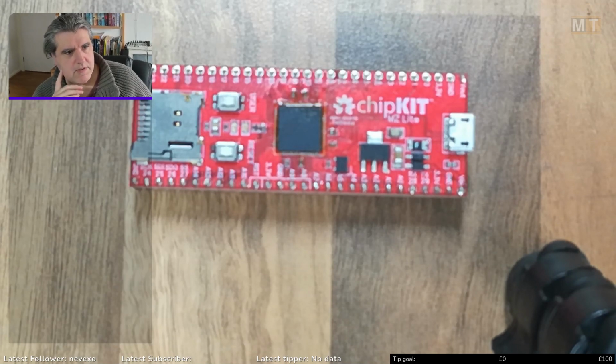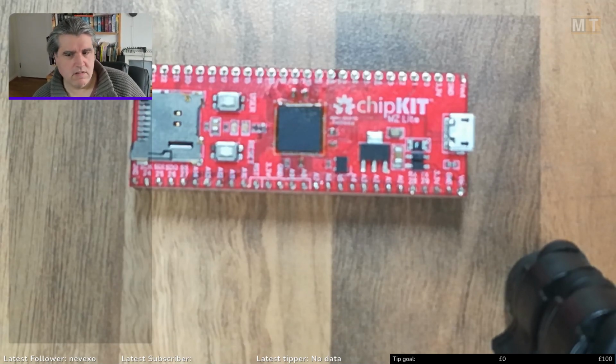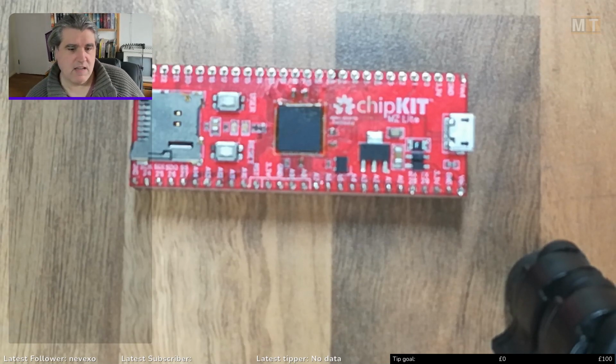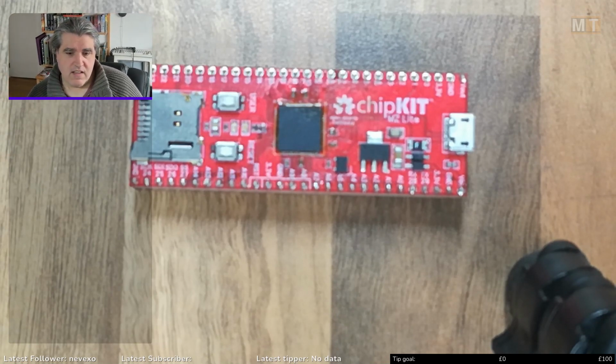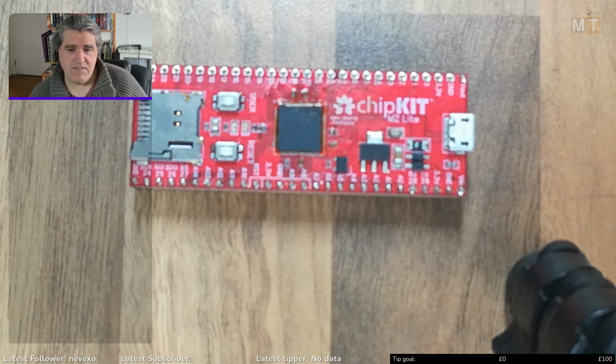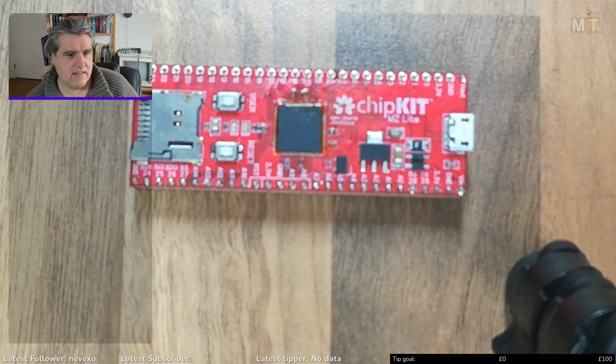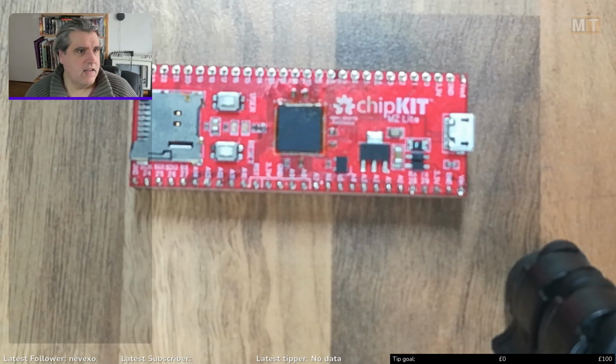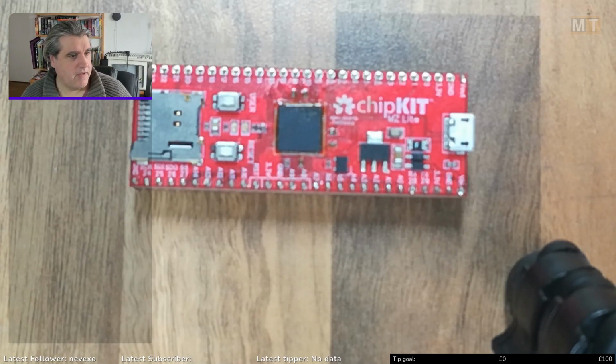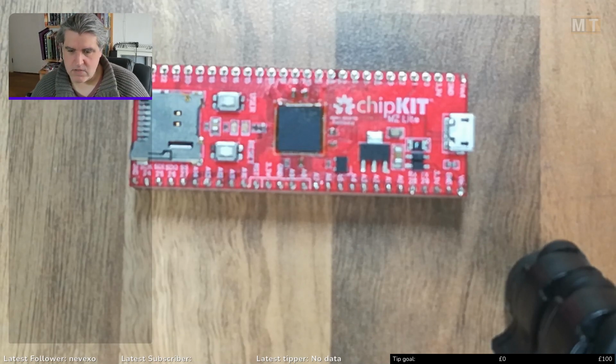If you're sending more than just one byte, you've got to work on packaging it and creating a protocol, and you tend to have overheads and inefficiencies where you end up sending data as ASCII, using twice as much bandwidth as you really need. I'd like to keep this as light and efficient as possible.